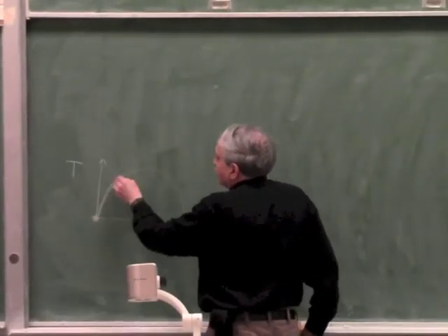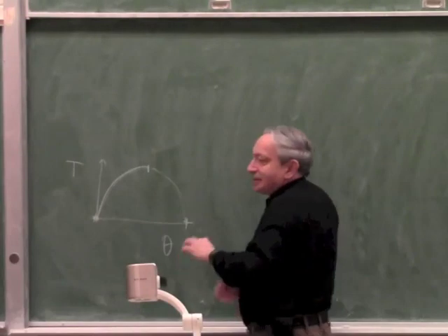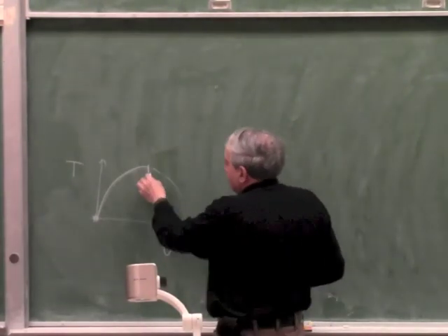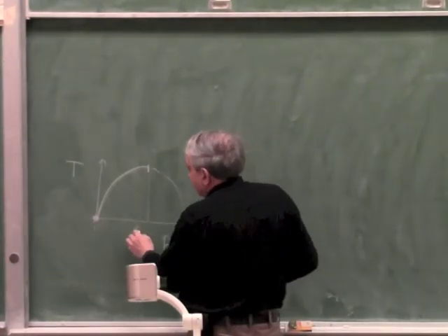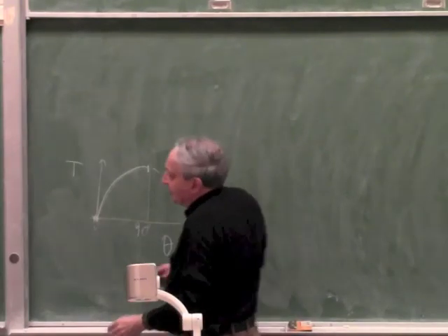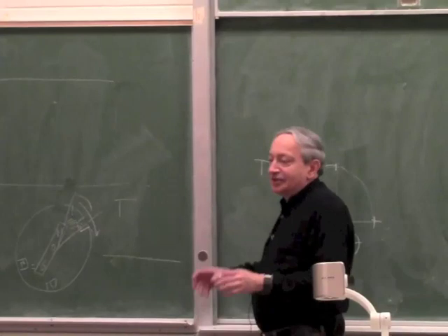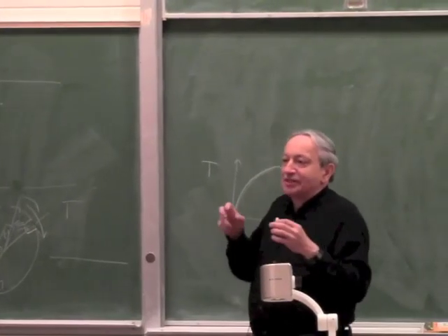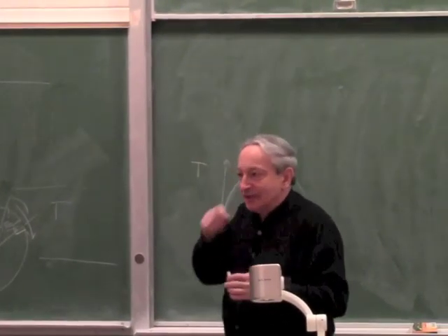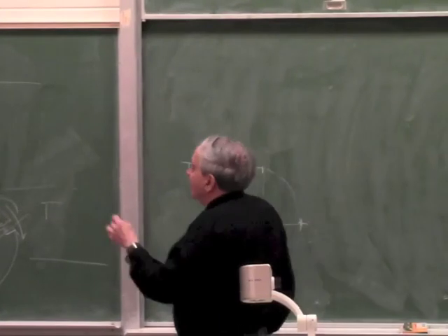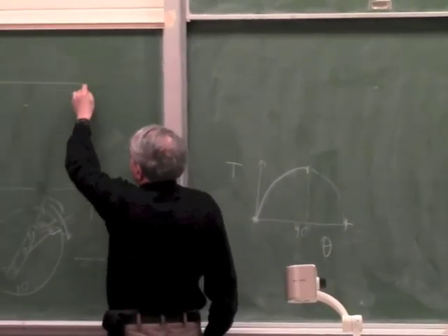But you can only use this part, because here it collapses, it can snap over. So you can really only use power angle from 0 to 90 degrees. And as you increase the torque, it starts winding up until it breaks lock. And when it breaks lock, it starts vibrating. It loses torque, just like a stepper motor when you stall it or when you try to run it too fast. So what really happens, it doesn't go down.